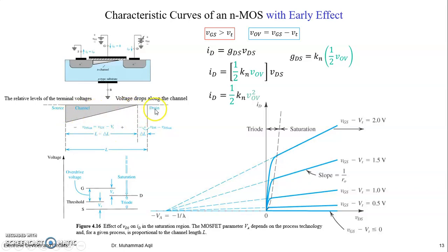Obviously current flows because of the applied voltage, right? High voltage charges will be swept out. But this effect is called channel length modulation, and because of this you are having a resistance between drain and source, and because of this you are having a slope in ID versus VDS. As you increase VDS, your channel pinching off effect goes back, length modulated, having a resistance between ID and VDS, current increases but slightly, so it means you are having a slope here.